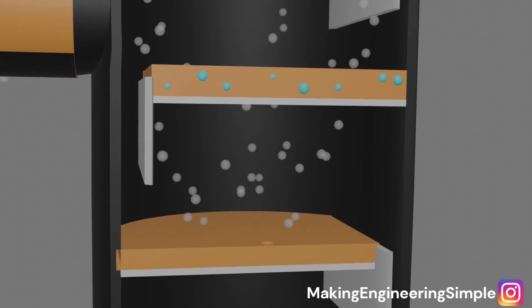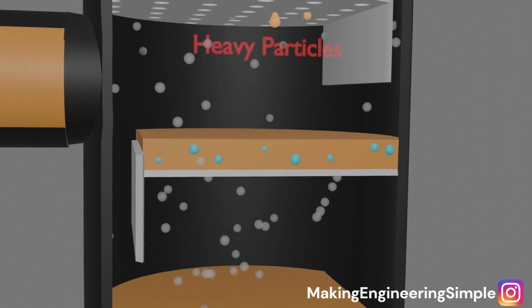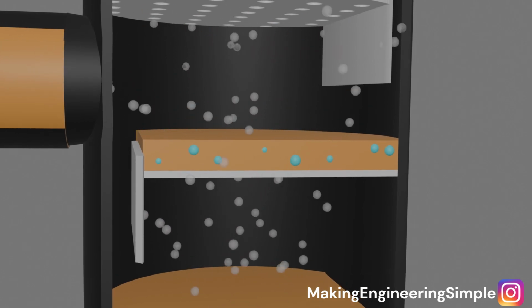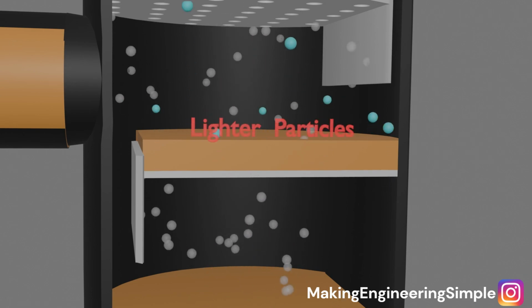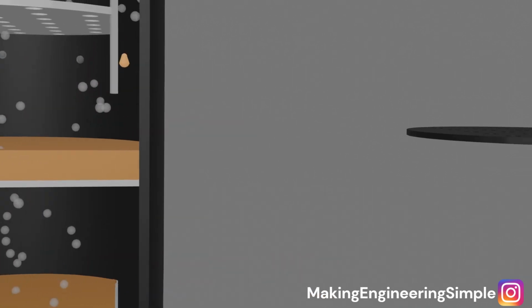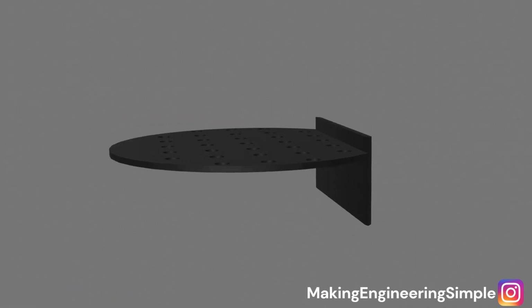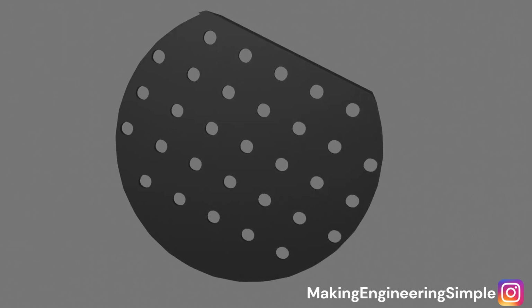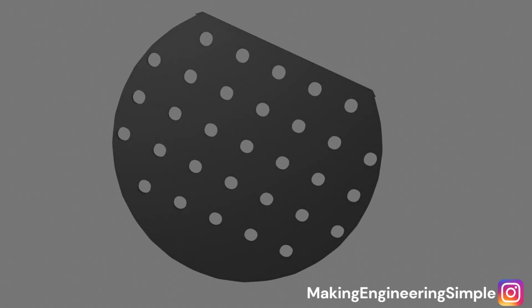As they mix, heavy particles drop out of the vapor and into the liquid, while lighter particles boil out of the liquid and join the vapor. In this specific column, we are using sieve plates. While there are several different types of trays out there, the sieve plate is a simple, effective way to provide the massive surface area needed for this transfer of heavy and light components.